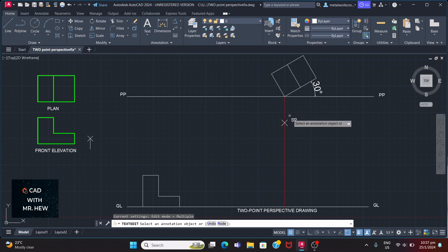All right. So ready now. What we'll be doing now, we'll be drawing a parallel line to this side that is highlighted from the station point to intersect the picture plane. Now, if you were using drawing instruments, you would use two set squares to draw this line parallel from the station point. Or you would have used a t-square and a 30-degree set square.